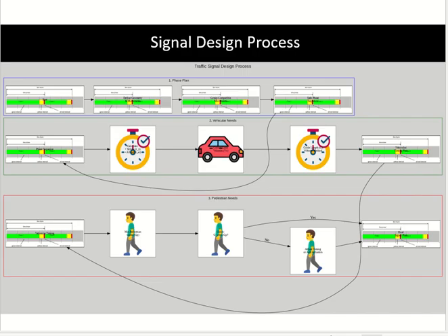Then after you find out the cycle length, you find out the total green time. What is total green time? You have lost time and you have the full cycle length. From the full cycle length, you subtract the lost time. This is your full green time. Clear? And then you divide this green time into different phases.